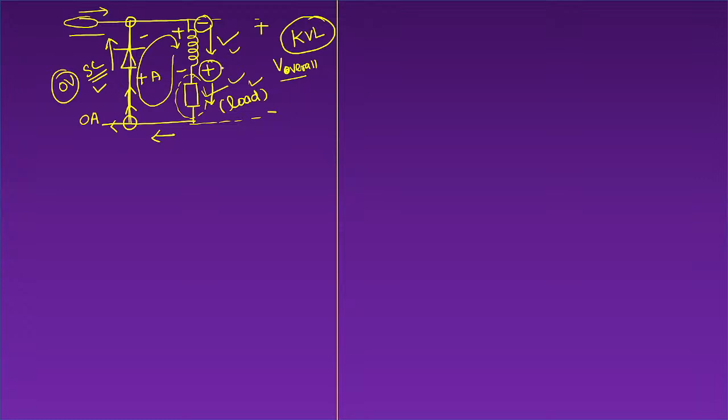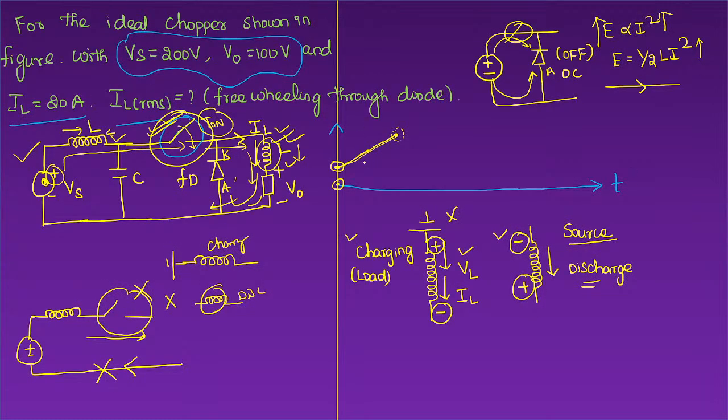Okay, sir. So as long as we have understood the second process, now what will happen is the inductor will be continuously discharging and the current will be flowing through the freewheeling diode. Initially your switch is on. Current through the load was continuously charging. Now your current is discharging, but this discharging will be happening through the freewheeling diode. Freewheeling diode is on now, switch is off. Yes or no? This is the off time period of the thyristor.